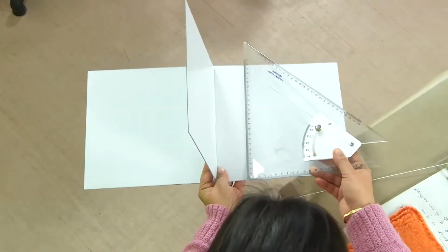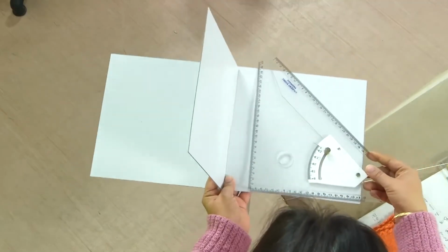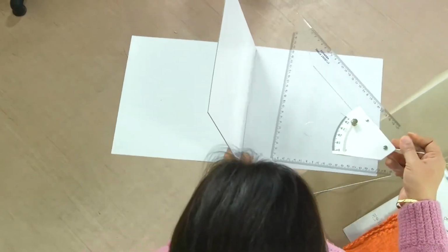So let us quickly understand this by visualizing it with the help of this quadrant system. So this is our quadrant here. We have, say, a triangular plane here, which is a flat plane. Now if we kept it like this, it is perpendicular to VP and it is parallel to HP. It could be at any different height, it could be touching the VP, it could be in HP, whichever way, but it remains parallel to HP. So what do we see? We see the true shape of this plane in HP, which is the reference plane to which it is parallel.